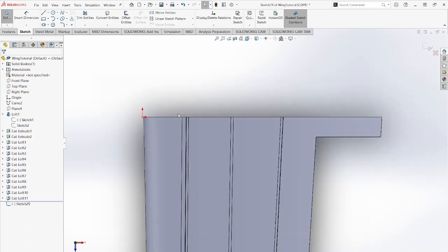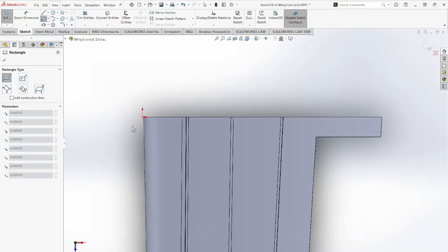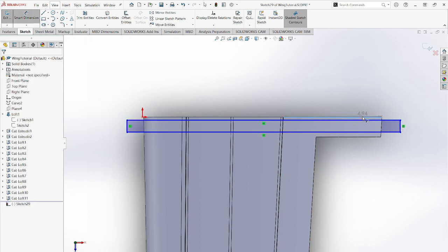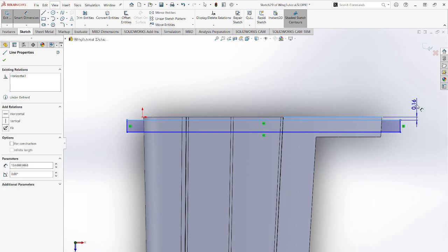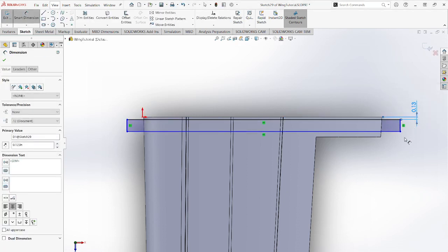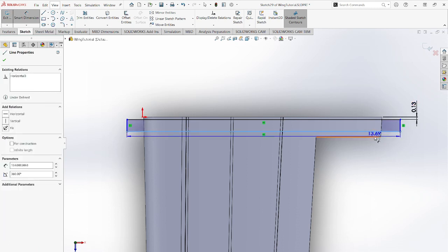We'll start by locating any fixed geometry, and essentially each slice is just going to be a big rectangle. And we're going to dimension these rectangles relative to where we want our ribs to be. So each rib is 1/8 of an inch thick, because that's the size of the wood that we have in the shop.